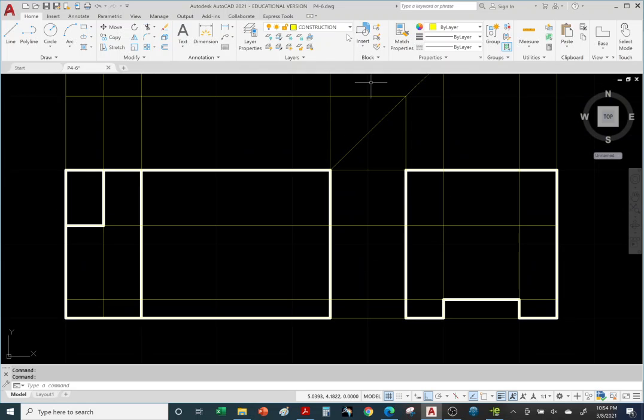Okay, so let's go to the red hidden layer. Okay, so here's the opening, that tunnel. We can see it in the right side view. Line command, and from this corner, I'm going to turn on Object Snap and Ortho. Okay, so there's our red hidden line, and right click enter, and let's go ahead and shorten this to the correct length, and there it is. Hit escape on the keyboard, and we're done with the front view.